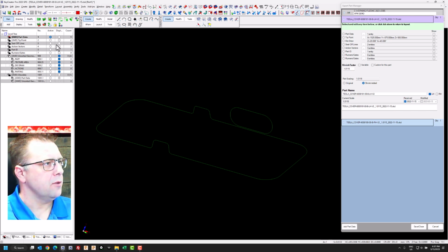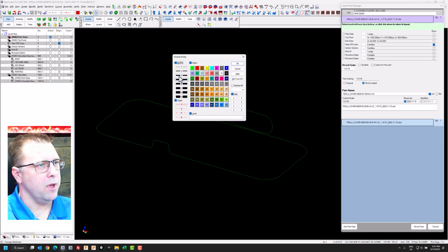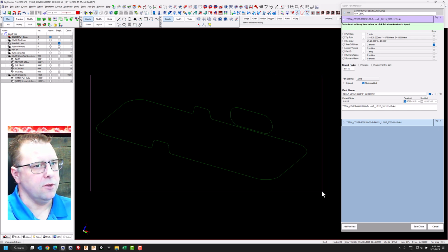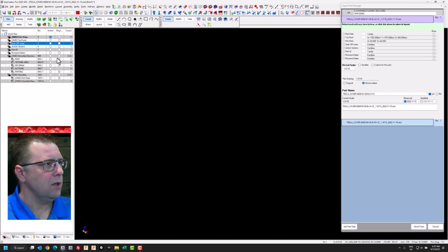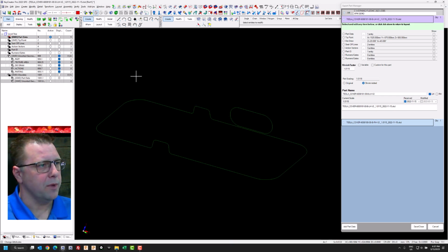So if we compare the parting line, seal off lines, and now maybe the seal off lines for our job, we actually want to make them thick. Then in the job they'll show up a little bit better. And I'll make the lines in the new file a different color so that we can compare a little bit better. So you're free to do any kind of manual changes you want to these files. You can set the entity attributes as you wish in order to interrogate the file a little bit better.